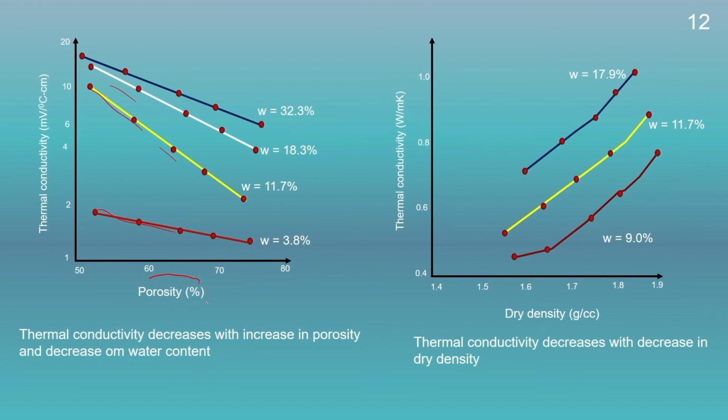Since with increase in the porosity, the amount of void present in the soil will increase, the particle to particle contact will decrease. As the particle to particle contact decreases, the amount of heat transfer from one point to another will also decrease, as the conduction phenomenon decreases.